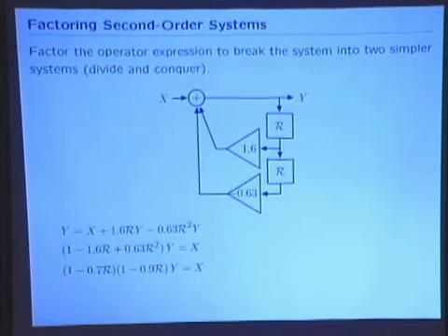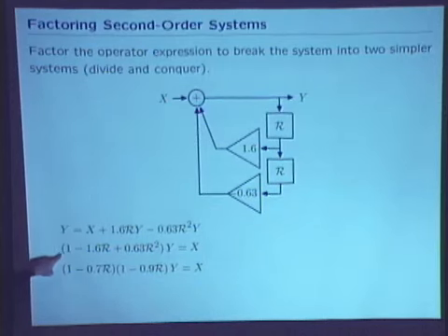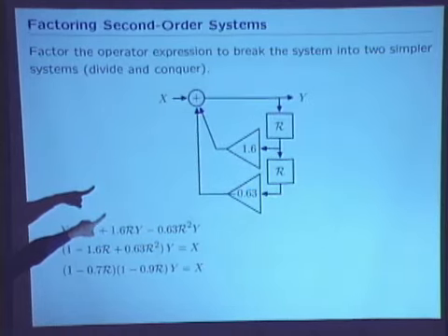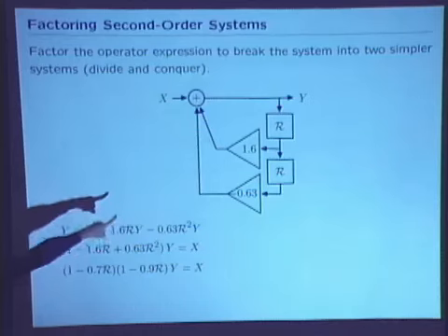However, this is where the polynomial stuff becomes useful, because I can think about tricks I can do with the polynomials, which you all learned in high school, so you all know how to do that. We can think about this complicated system in terms of simpler systems that can be represented by one pole. For example, one of the more powerful things you can do with a polynomial is factor. If you factor this polynomial, this is a simple representation for that. I can just read that straight off the block diagram.